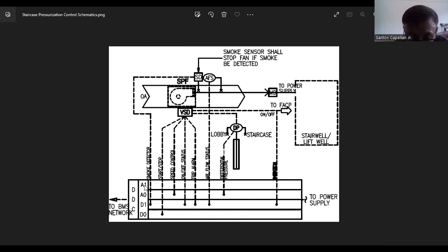Then analog input, but of course there should also be an analog input. So what will be your controller selection? At least two digital outputs, then 1, 2, 3, 4, 5, at least 6 digital inputs, then at least 3 analog outputs, then at least maybe 2 or 3 or 4 analog inputs, for future use.